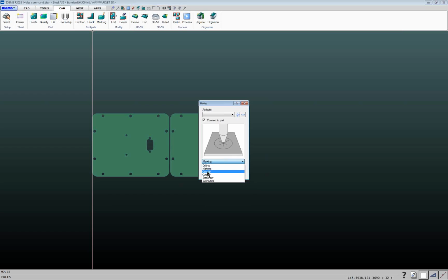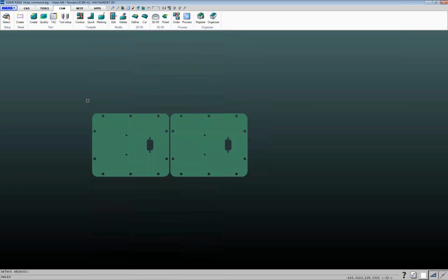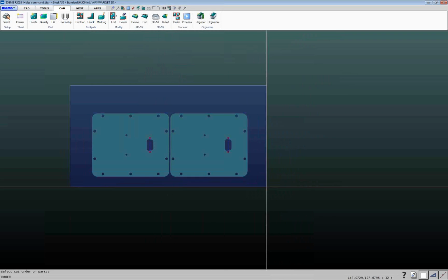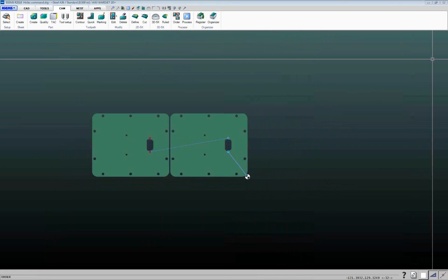You can just do a circular pierce at a location. So if you want to go around and make a bunch of circular pierces, you can do that without doing the lead and actually cutting the geometry. The cutting option creates a very nice hole, what they used to call their high quality hole option. So if we do this one and we'll again choose that hole size and click on there, what we'll see is it's going to end up going around these holes 3 times.